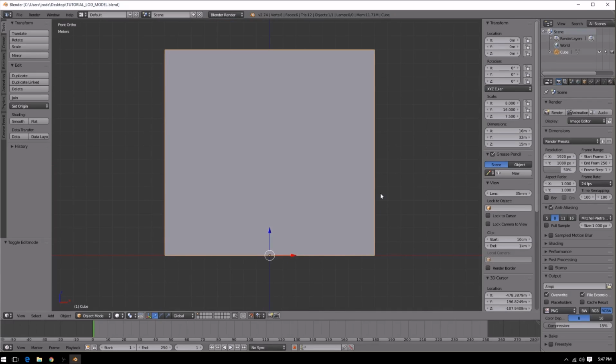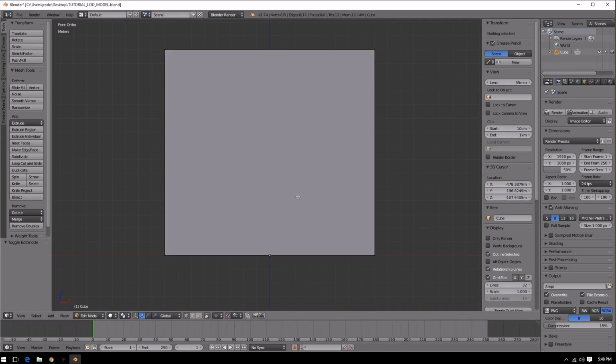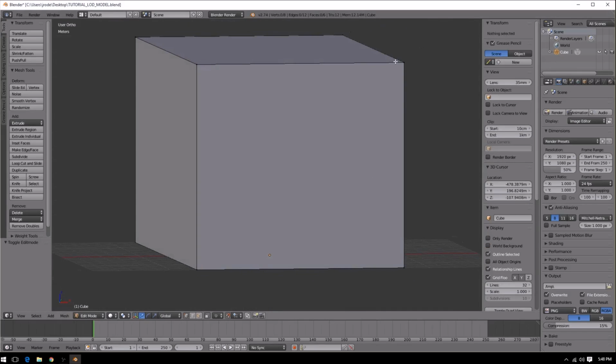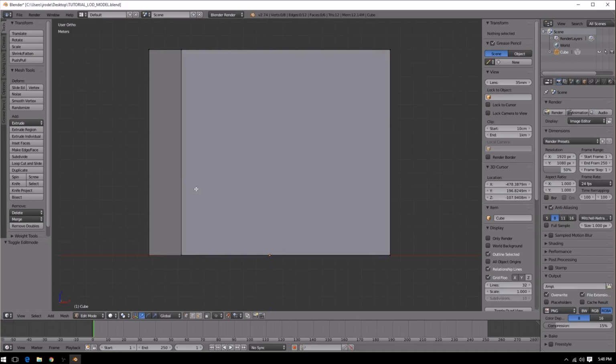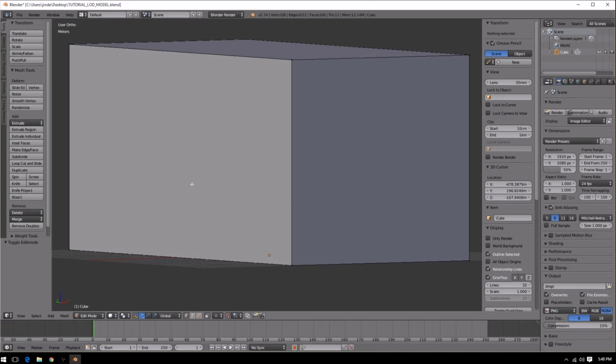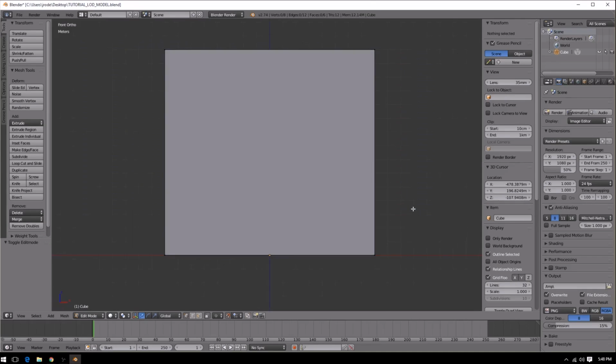Oops, I think I counted one too much. And the first tool I'm going to show you is the loop cut tool. To access the loop cut tool while you're in edit mode, which I haven't been in yet, I just click Tab to get into edit mode. So now we have vertexes and everything manipulatable. And the loop cut tool will basically make a line or a new cut around this mesh so that you can manipulate it. And it'll make more sense when I do it.